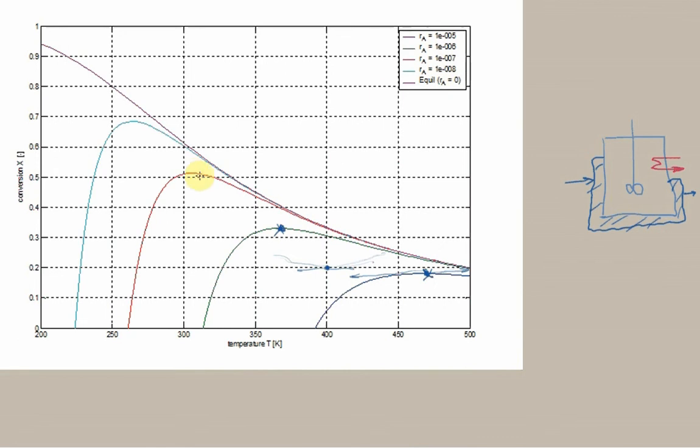And then on the red line also, over here to the left, it's closer to that, which is a lower rate, and to the right, it's also closer to that, and that's a lower rate. So that's again a maximum, for the same reason. So you see, for the batch reactor, it looks like our maximum rate region is this locus of points. So we would like to stay on this set of points here.